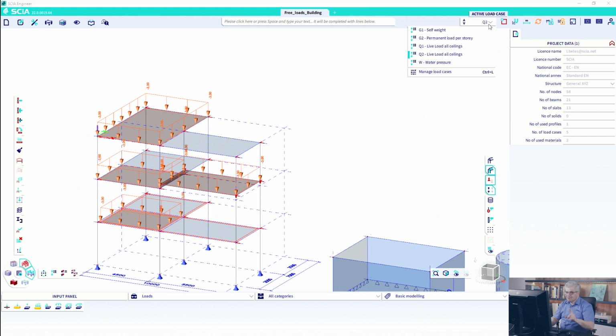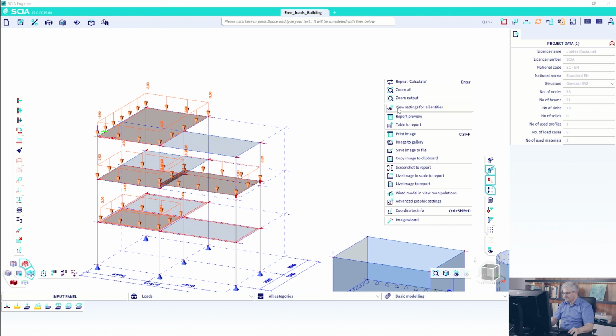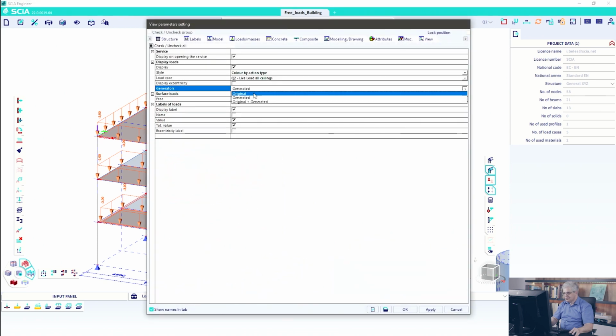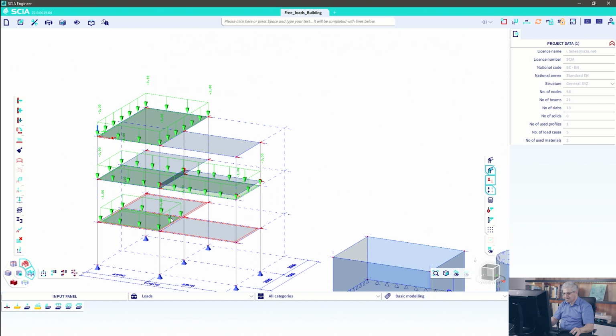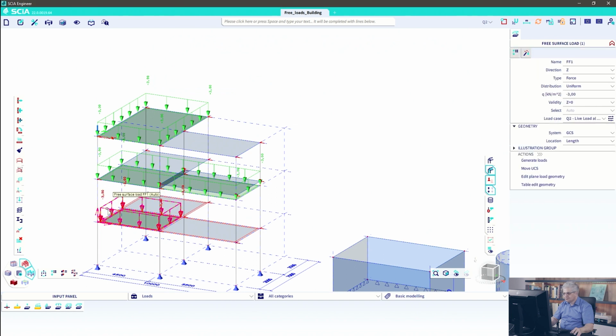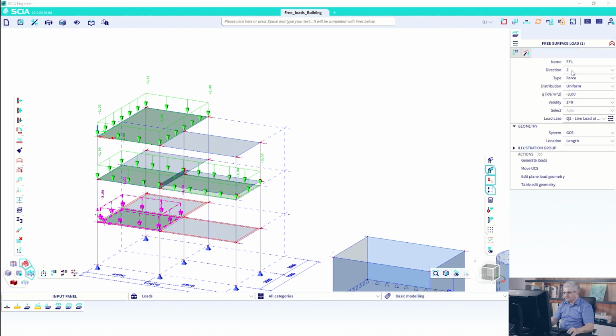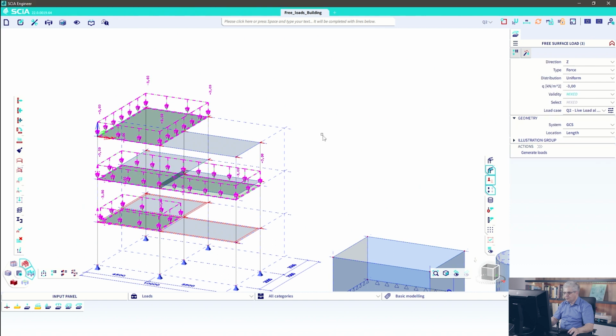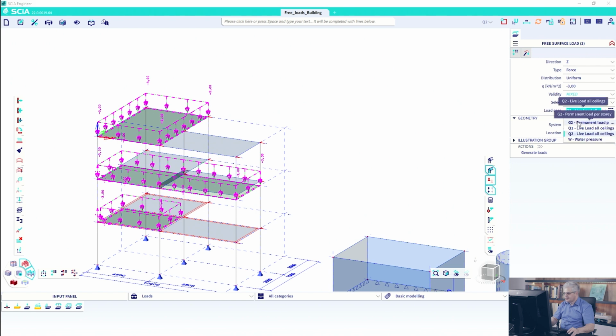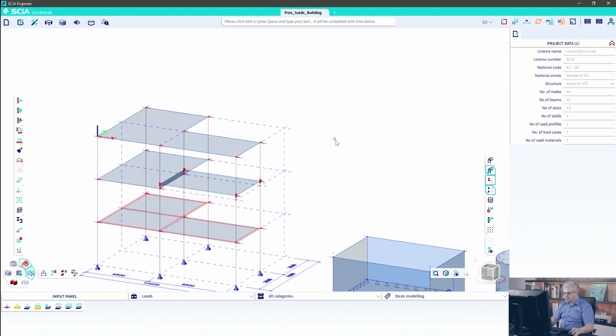This is a wrong load case. So then go back. I go to original, apply, select all these loads. You can select, for example, right mouse button, say expand selection, then all loads which act in that direction will be selected, and we change the load case to G2.